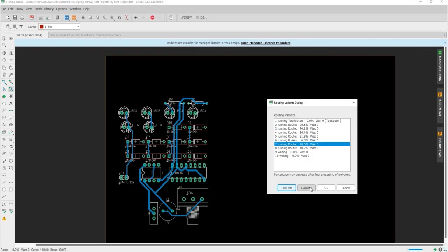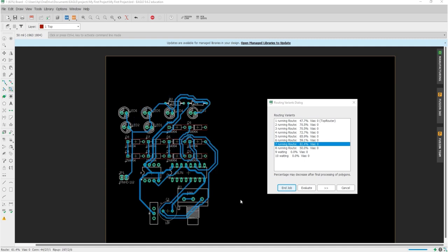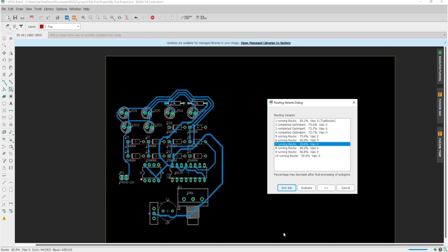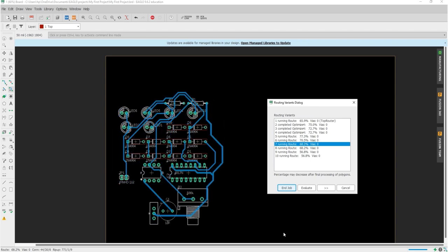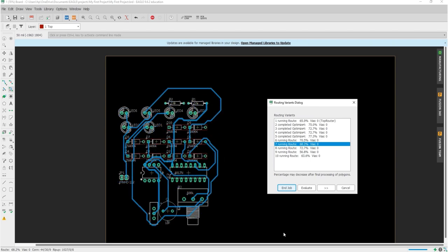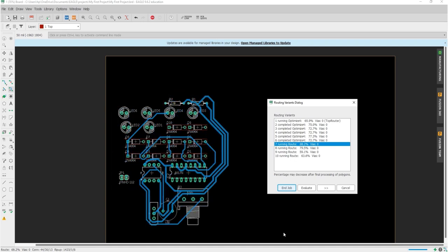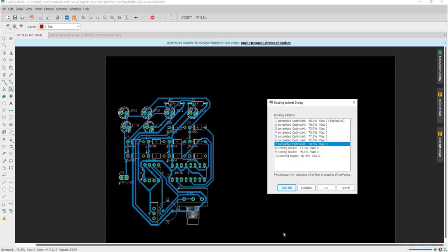Autodesk Eagle also provides us with an auto router feature to ease the board layouting process. The effort of this process can be set based on our need. The higher the effort, the more detail it will give and the longer time needed to finish the routing process.